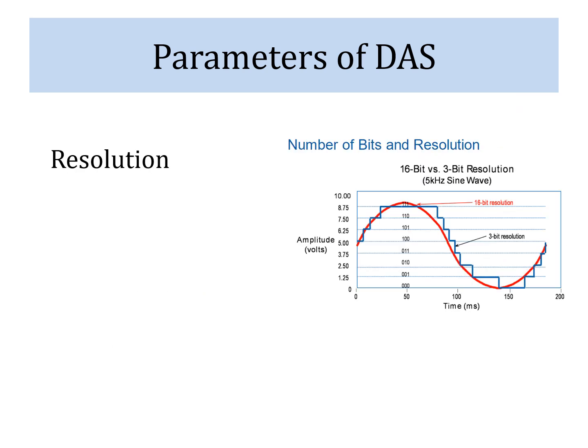So, coming to the last parameter, that is resolution. It is again similar to our system design, that resolution is very important. If I try to compare a 16-bit versus 3-bit resolution of any sine wave, if I try to convert any sine wave into digital one, if I have only 3-bit conversion, the signal will be very much square or rectangular, because we have very few bits to convert this signal. But as we keep on increasing the number of bits, the levels will start increasing. Let us see how it happens.